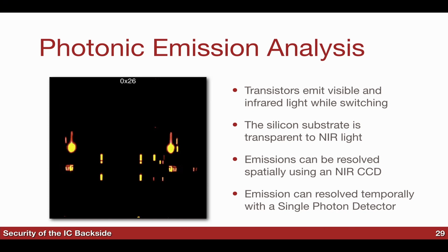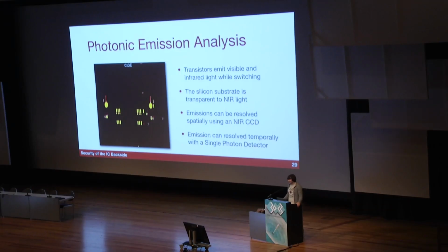At the beginning, when we were starting this research, this is what I expected to happen from the very beginning. And then it took us like a year to find an area of the chip where you could actually see the data bus like this. This is a region of the chip where the data bus comes in and it's addressing the SRAM. On the bottom right, you see the lower address bits, et cetera. Or sorry, this is the data bus, but it's kind of shared.